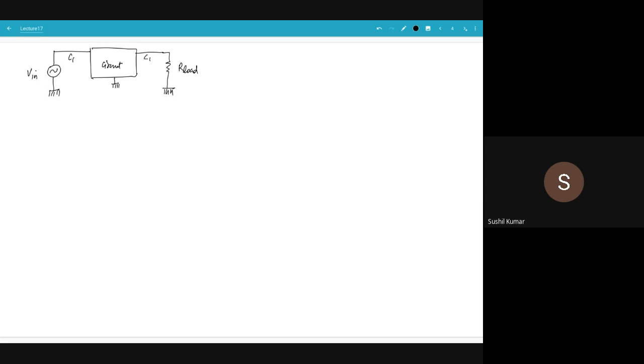Where is that conductor? So there is one conductor here. This ground is the second conductor. That is exactly what I just want to show you. So the second conductor is this ground, which is C2. There is a second conductor. If you're on your PCB, you put a wire on one of the holes and take it all the way to your circuit. On the other side, this is one conductor, but the other conductor is under the PCB, which you don't see, the ground plane. So there are always two conductors when you are transferring electromagnetic energy or electrical energy.